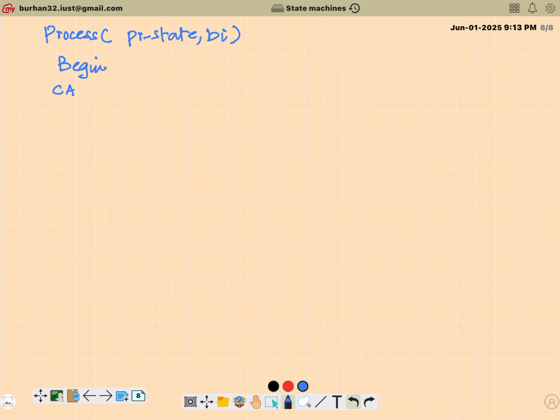So case with previous state as my identifier is. Then I will define the multiple values that this identifier can take, starting from the first one when it has a value of A. So when it has a value of A, the output, let's say you have called it B naught, will be 0. But we also have to define what will be my next state.